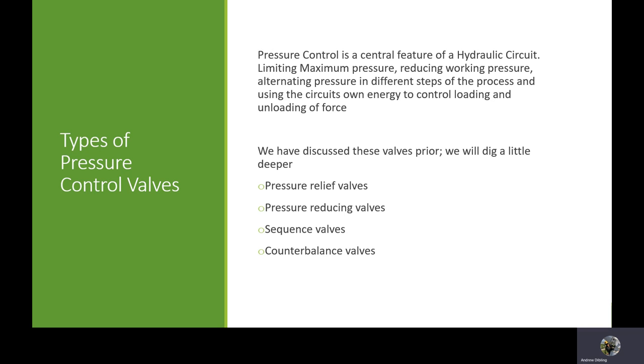Counterbalance valves are kind of a way of a system check to make sure that the system doesn't overdrive in one direction, a motor doesn't run too fast, it has braking elements in it. It's quite an interesting circuit and has various applications.